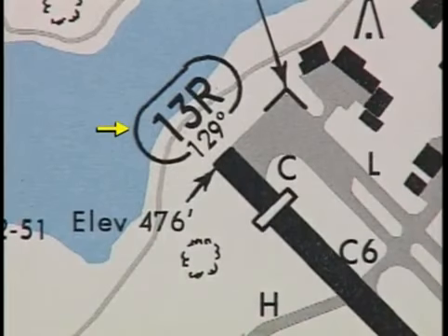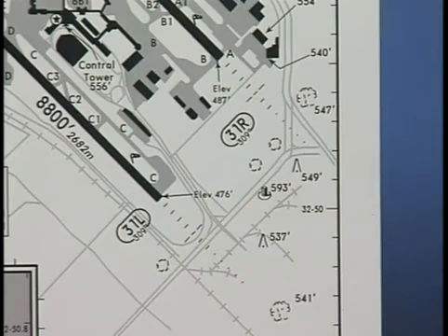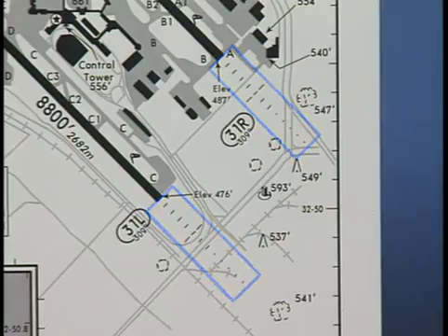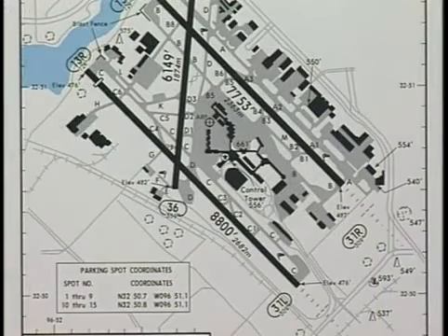The runway number, the runway elevation, and when available, the exact runway magnetic bearing are depicted on the ends of the runways. There are several symbols included in the plan view to help better orient you with the airport environment. These symbols include a bar across the runway, indicating a displaced threshold. If an approach lighting system is installed, a symbol showing the lighting array appears next to the specific runway. When appropriate, taxiways are also labeled with letter designators.